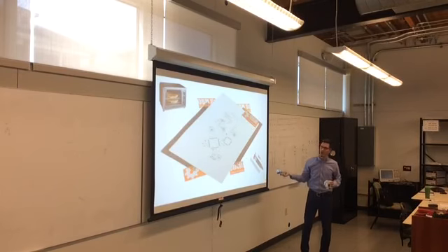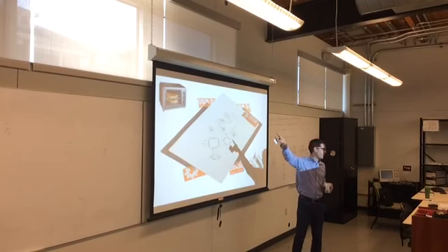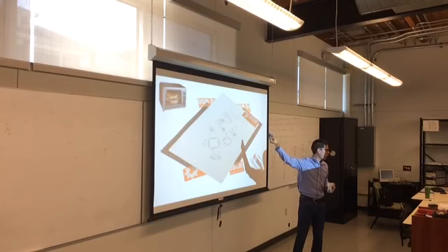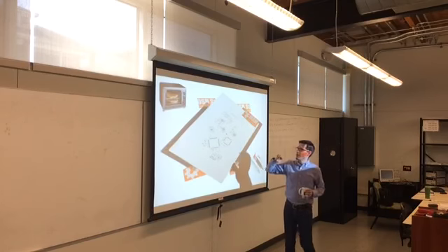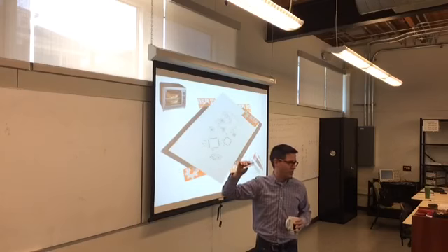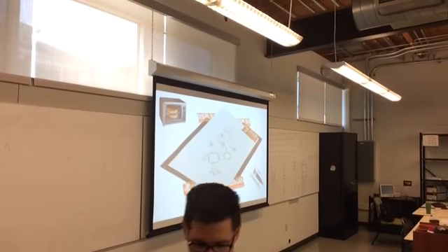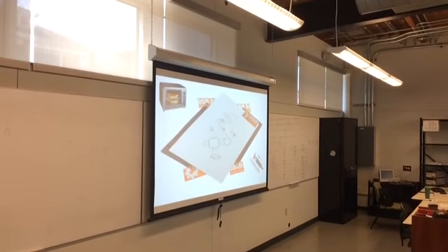You've got your liquid solder, and then you put it in the toaster oven. Well, yeah, the pizza. This is why I wrote very large on that toaster oven, no food. Because it's just been full of student boards over the years. You can use just a basic toaster oven and turn it up temperature, down temperature, and it'll work. We do have a really nice toaster oven that will get working.